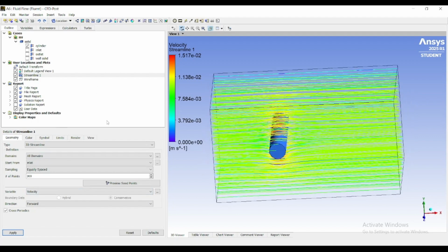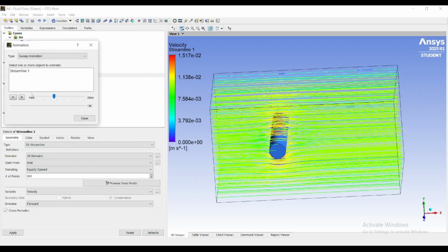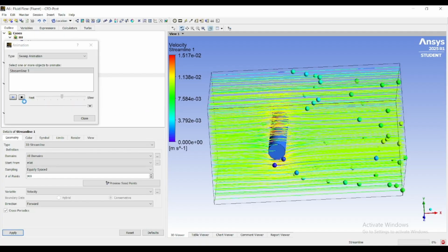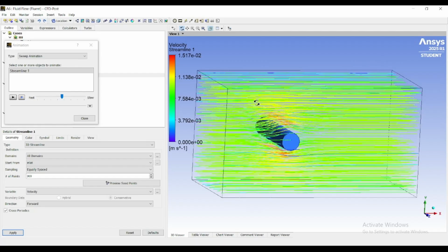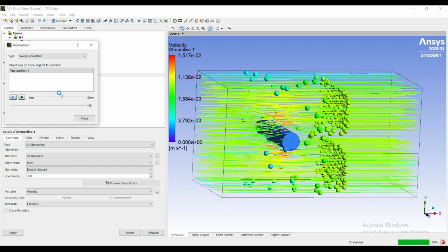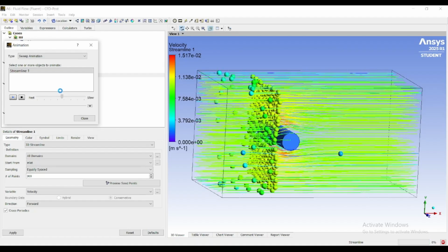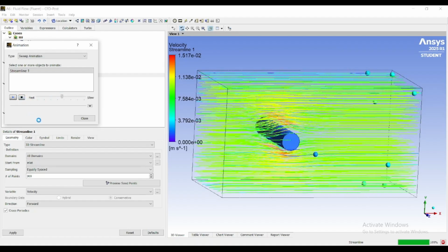Path lines and vector fields help you understand the direction and magnitude of the flow, while streamlines visualize the curvature and interaction of the fluid layers around the cylinder. Pressure contours, in particular, vividly display the front stagnation zone and low-pressure wake, giving a direct visual representation of drag-causing regions. To make your analysis more informative, you can label the color scales, adjust contour intervals, and use consistent color themes for different cases. This ensures easy comparison when you change parameters like velocity or turbulence models.